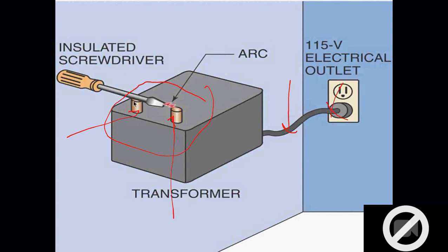So, again, screwdriver method, you're going to see technicians use it. I think we actually do have you do one in the shop just so you're aware of how it works, but it's not something you want to do frequently because it's too easy for you to get a screwdriver that has a cracked handle. It's too easy for you to touch this metal part while you're doing it, and it's just not a good idea. Questions on that?